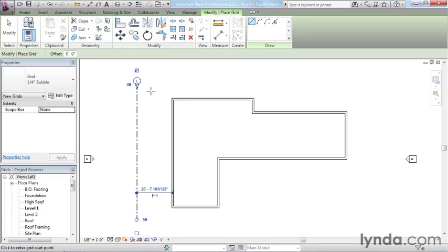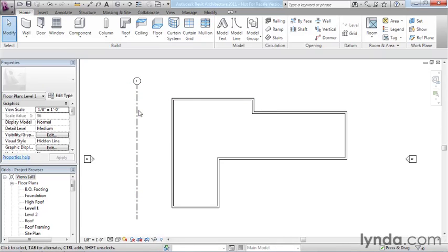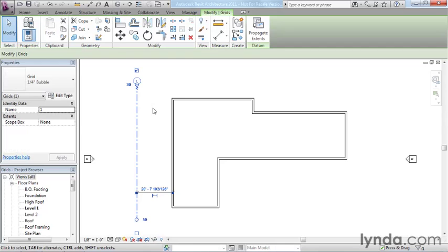Now it is possible to actually change that behavior after the fact. And one of the reasons that I drew this grid off to the side was to point out some of the controls, similar to what we had in Levels, in the Levels movie. We have the little open circles that we can use to change the length of the level. And talking about the bubbles, we have these little check boxes. Now, the little check boxes actually appear in Levels as well, so you can do the same trick there. If we want a bubble to appear at the bottom, we can simply check the box and it will show a bubble. Likewise, if we want to hide a bubble that we previously showed, we can check the box and it will hide the bubble. So if you want them at both ends, you can have them at both ends or at either end.